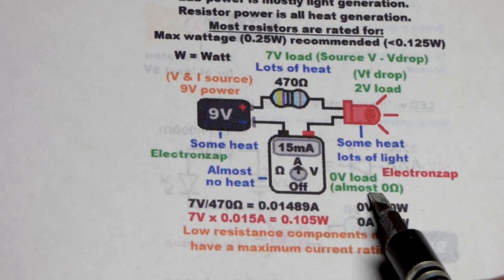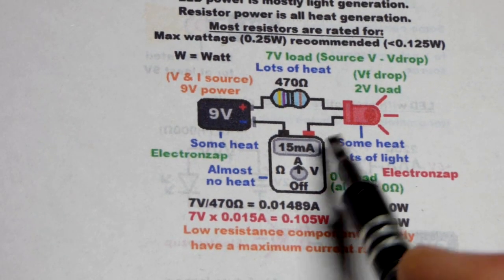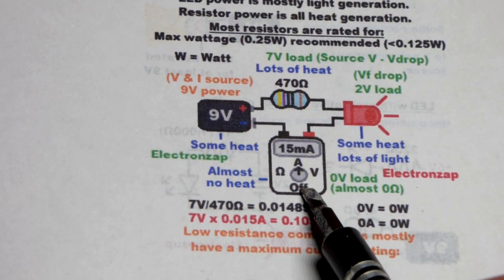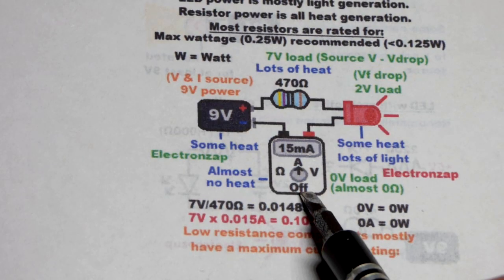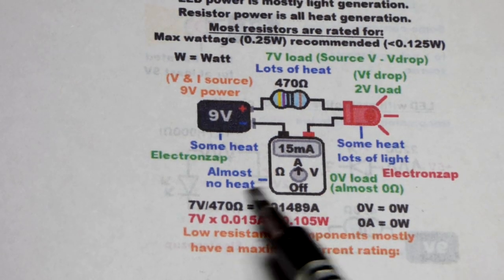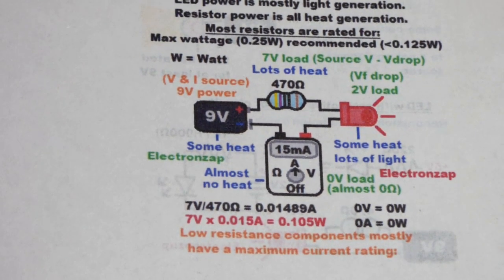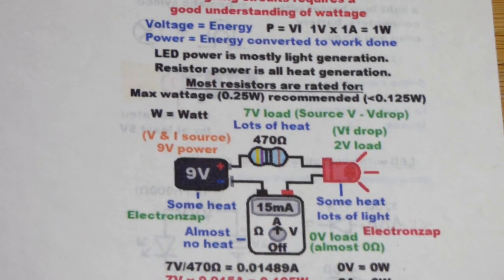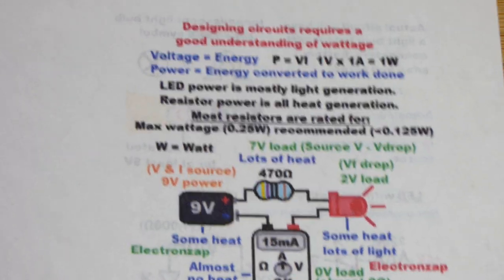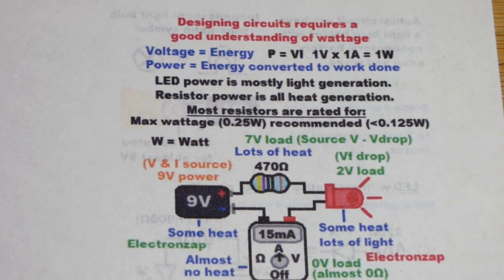So it should not really be heating up, especially at low currents. The ones that can measure like 10 amps of current, if you measure 10 amps, it actually builds up heat because of how much current is flowing. So you got to take short current measurements. But at these lower measurements, you got almost no heat. So in any case, very long video, but I just came across this diagram. Thought I would explain it all.